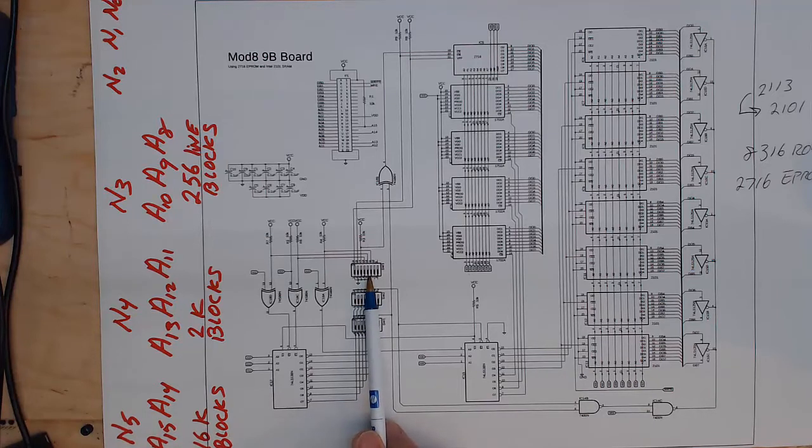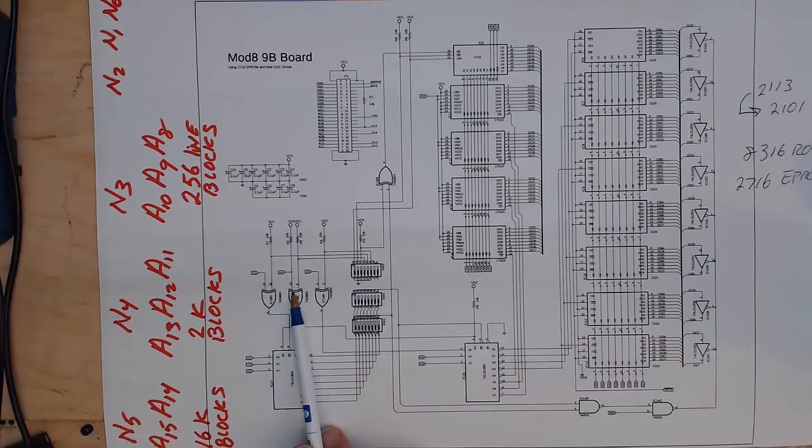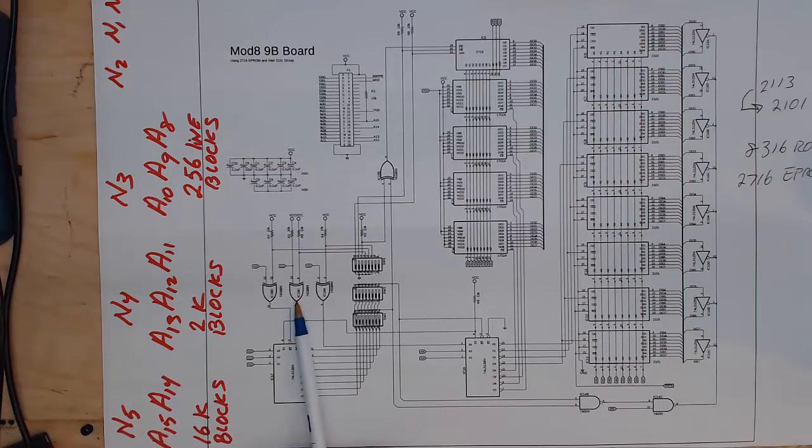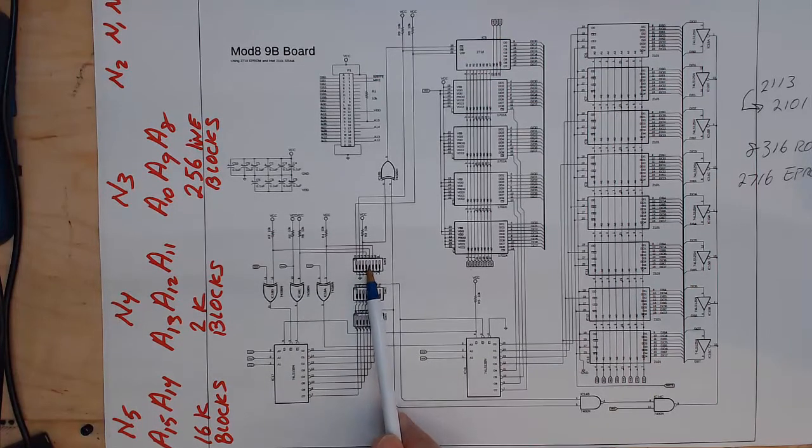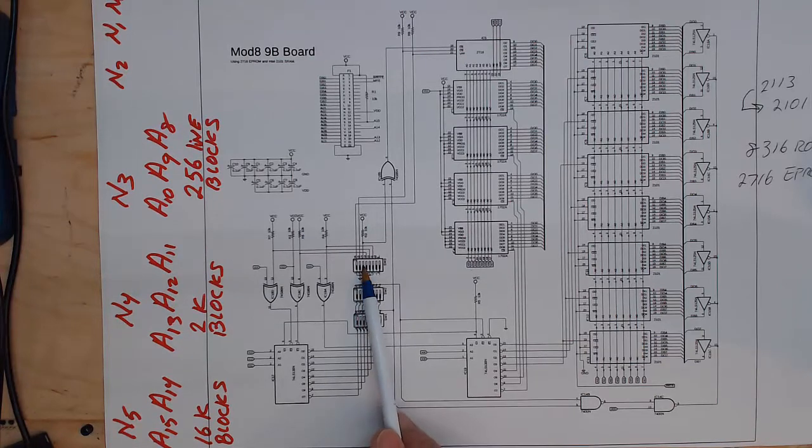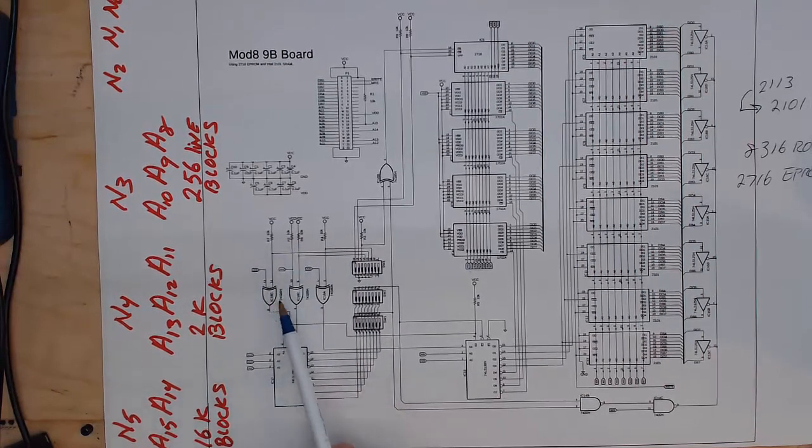So with switch 5 and 4, we can decide whether A14 and A15 are going to be either 0, 1, 2, or 3. And in this case, these 2 exclusive ORs, if you look back at my video that I did, number 38, I think, on the mystery of the magical exclusive OR, we know that this can be used in a few different ways, but in this case, they're using this as an equate detector. So they're basically saying when do these addresses, A14 and A15, match the dip switch setting. When the switch is on, it takes that line to ground, and when the switch is off or it's open, then these pull-ups are allowed to pull these high.